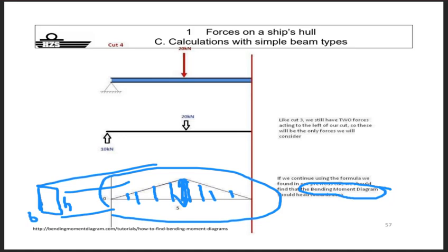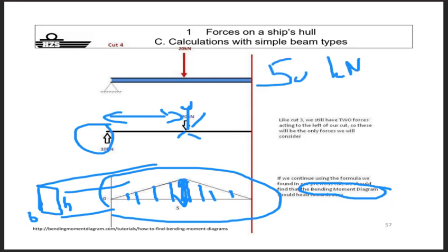How many kilonewton meter? 50. Thank you, Tristan. Indeed. Why 50? Because if you are positioned mid-length of your beam here, you take this force into consideration, multiplied by the arm. Exactly, so it leads you to 50 kilonewton meter. That's your bending moment. Yeah?